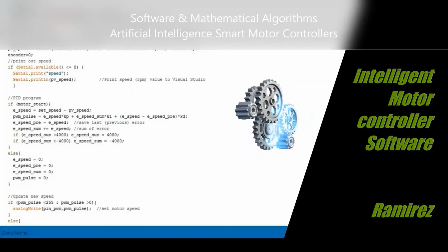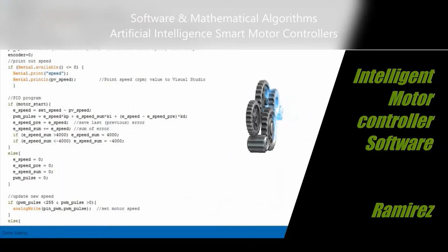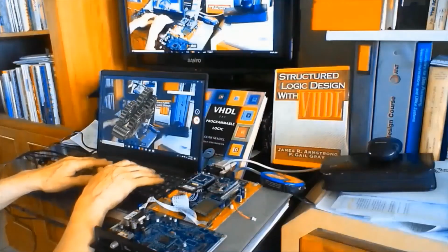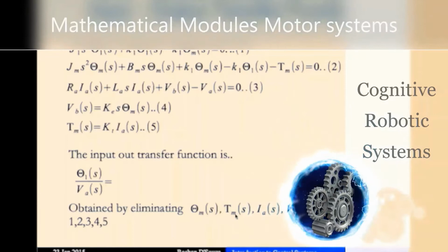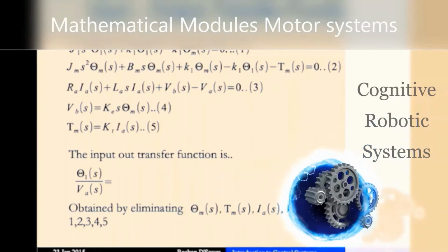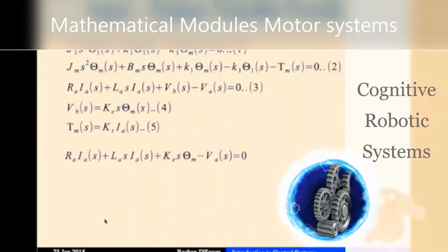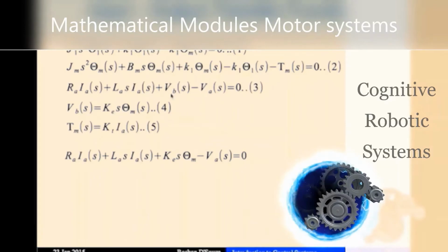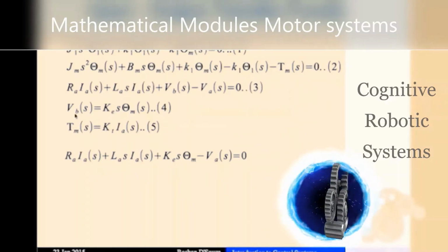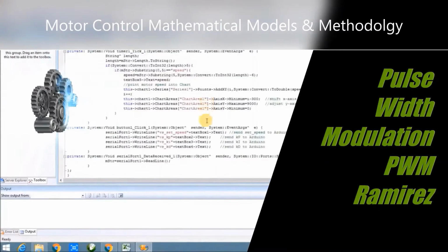The frequency determines how fast the pulse width modulation completes a cycle, and therefore how fast it switches between high and low states. It is done by cycling a digital signal off and on at a fast enough rate. With a certain duty cycle, the output will appear to behave like a constant voltage analog signal when providing power to the motor.